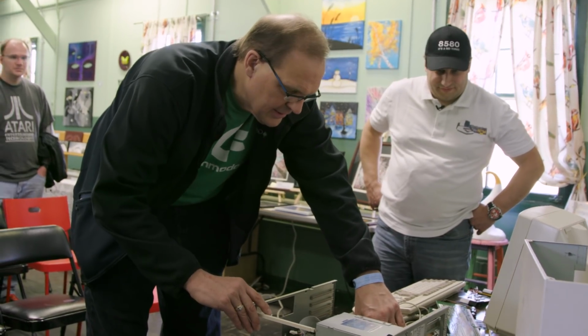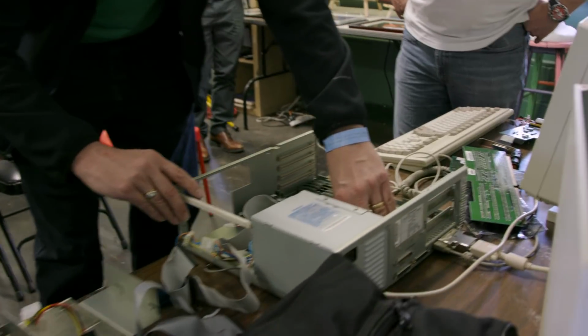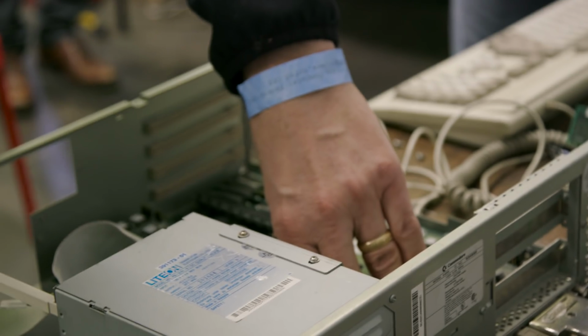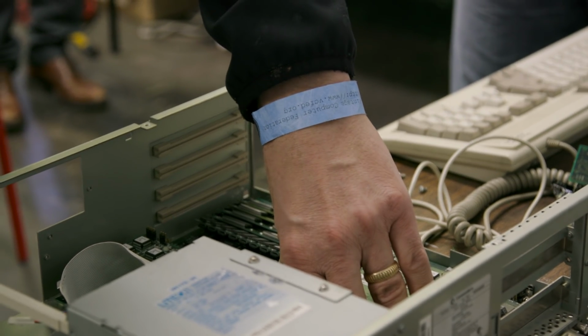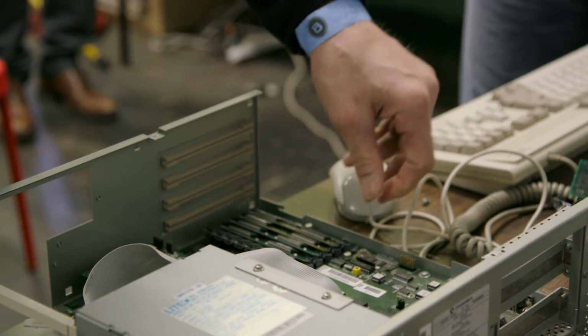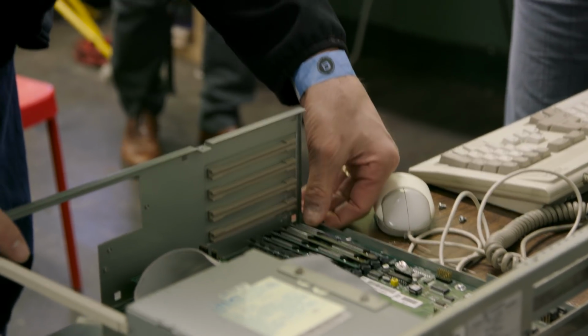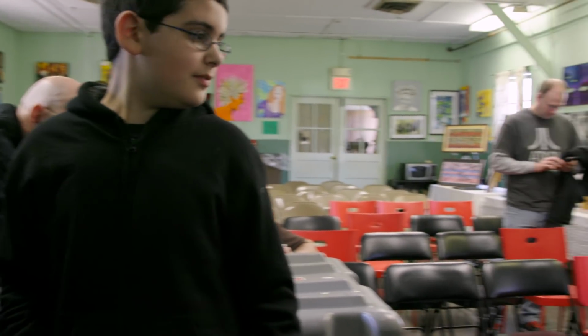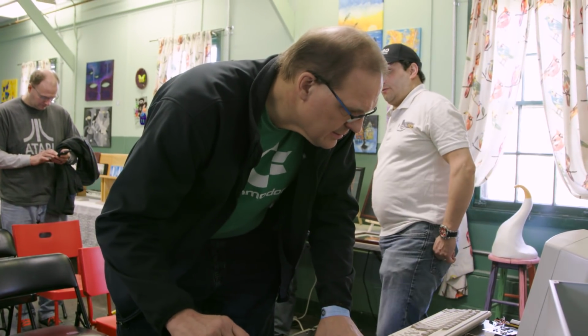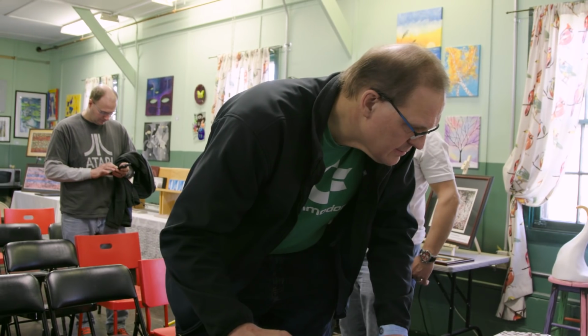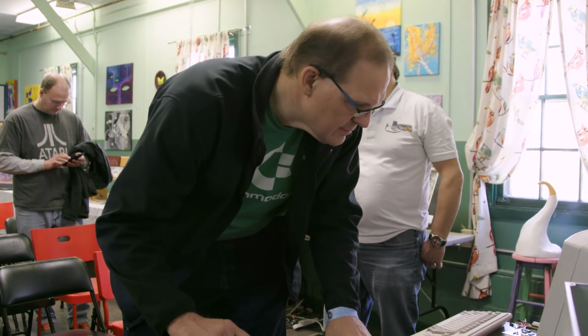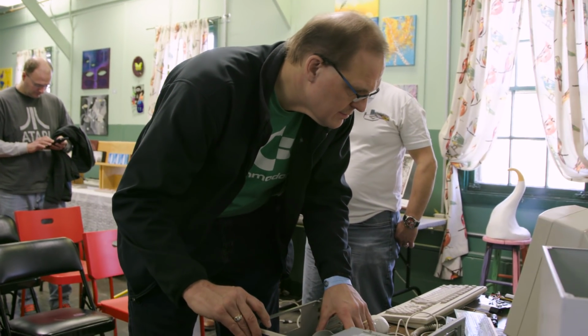Isolate the sockets? It's fairly well mounted. I don't want to flex it too much. But if you've got an intermittent trace or via or something, if you flex it a little bit, it'll do something different, right? How hard is it to take the board out? Pretty easy, actually. There's no screws holding it. It's just 4 or 5 plastic posts and the socket itself.